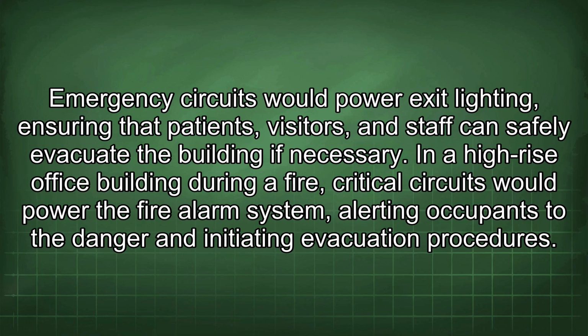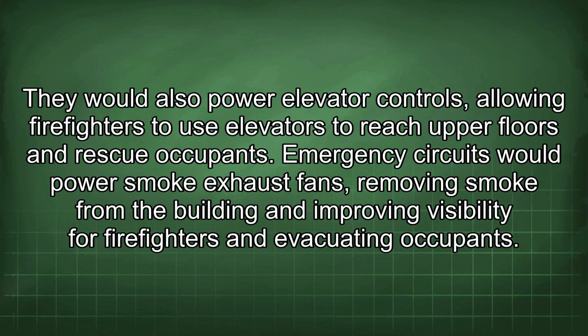In a high-rise office building during a fire, critical circuits would power the fire alarm system, alerting occupants to the danger and initiating evacuation procedures. They would also power elevator controls, allowing firefighters to use elevators to reach upper floors and rescue occupants. Emergency circuits would power smoke exhaust fans, removing smoke from the building and improving visibility for firefighters and evacuating occupants.